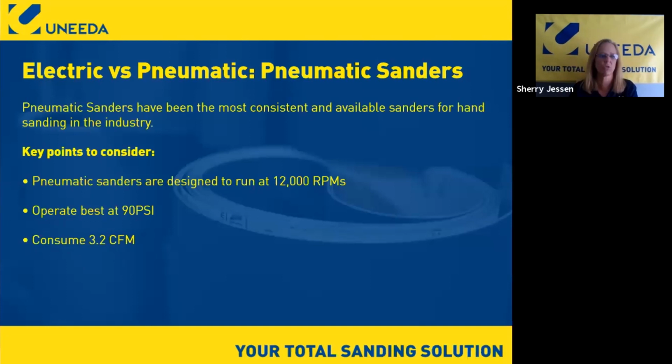Optimally, you don't want them to drop below 10,000. When you start dropping below 10,000, the pad starts to slow down and you get a drag on the pad. What happens is, one, you wear out the abrasive grain a lot quicker. Two, it's drawing much more dust, and you're loading so much more into your abrasive, so you're going through a lot more abrasive product. We'd like to see 12,000 RPMs, but we don't want to go below 10,000. That's the breaking point. You have to have it at least at 10,000 RPMs.